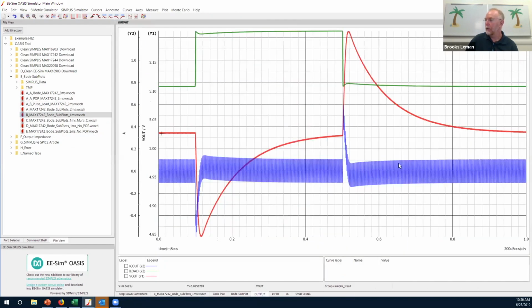So here's an example where we have minimized the delay time, we've minimized the pulse width, and minimized the stop time so that we show pretty much only the parts of the waveform that we need to see. We don't spend a lot of time grinding out static or equilibrium waveforms.